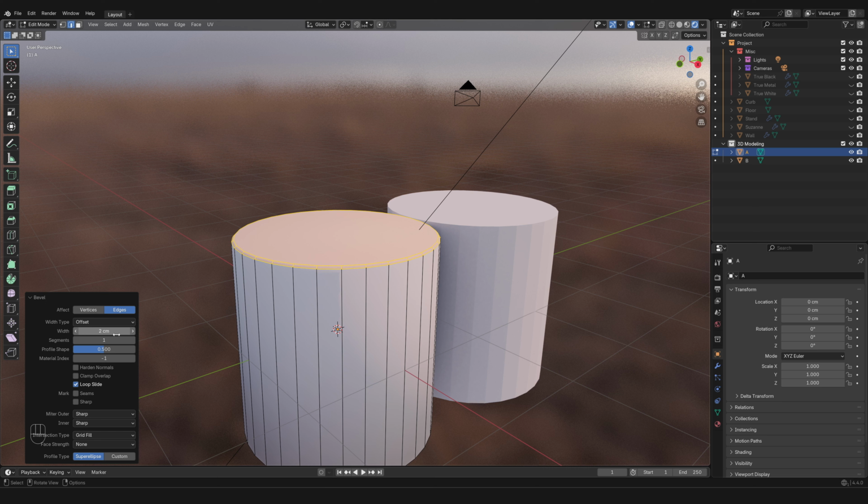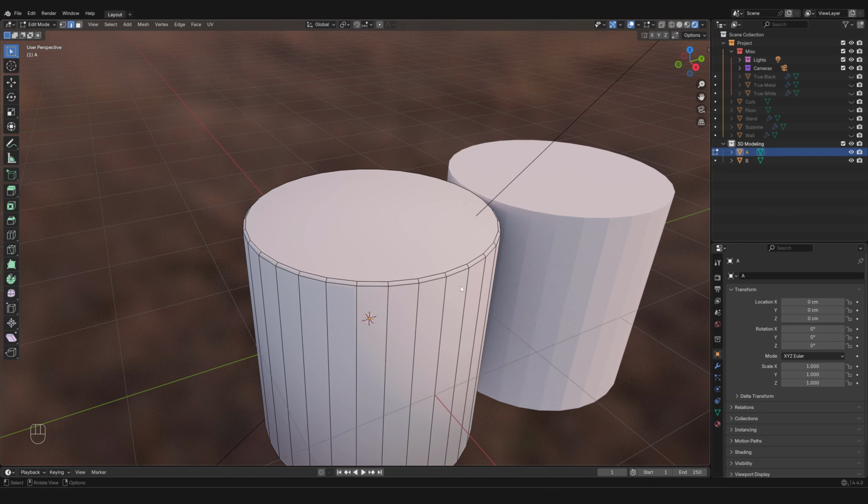Now the bevel command introduces a bevel, obviously, but you can think of it a little bit as the edge loop, with the distinction that instead of inserting an edge, you are inserting a whole set of faces. And so now that I have this extra loop over here, I would like to reiterate that if you press down Alt and you double click on the edge, it's gonna select the whole loop for you, as opposed to simply clicking on an edge and that will select the single edge.